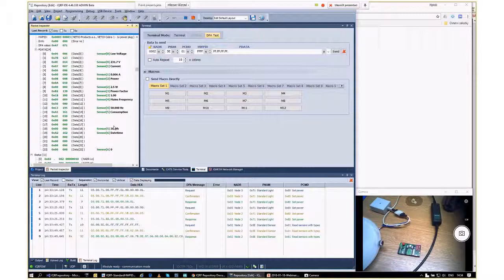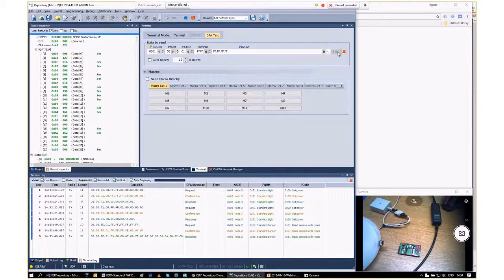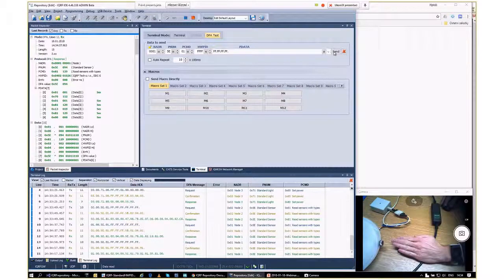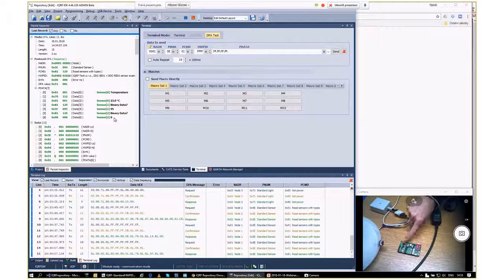We can also try to read another standard sensor. We don't care who is the manufacturer. And let's read this example, the IoT kit example from here. The temperature it says is 23, and the binary data is 19. It's a photoresistor. So if I cover it with my hand and start it again, the number should be higher. As you can see, 95. This number is the position of the potentiometer over here. So if I turn it the other way, we should get the maximum 227 value, I hope. Yes, we did. So this is the way we control the standard devices from the terminal.